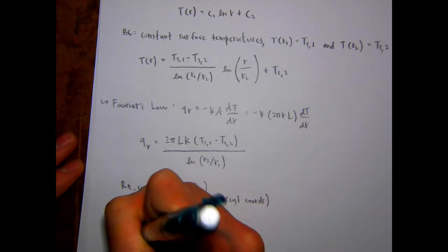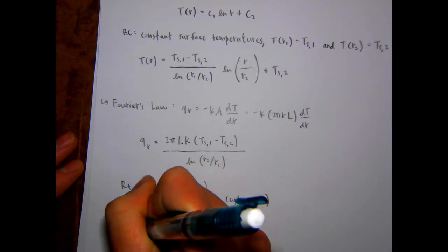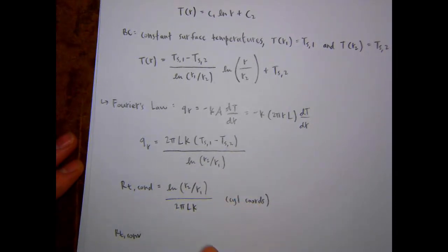So remember, we have convection boundary conditions for this problem, right? There's convection on the boundaries, but we took our boundary conditions to be constant surface temperature. We said we know the surface temperature at the inside and outside of the cylinder. So what we were doing when we derived the temperature distribution, if you go back to the derivation of the heat diffusion equation, was just looking at heat transfer via conduction in and out of a differential element, right?